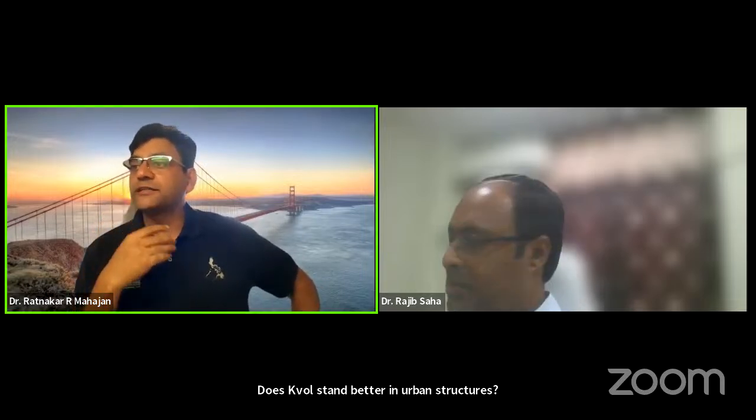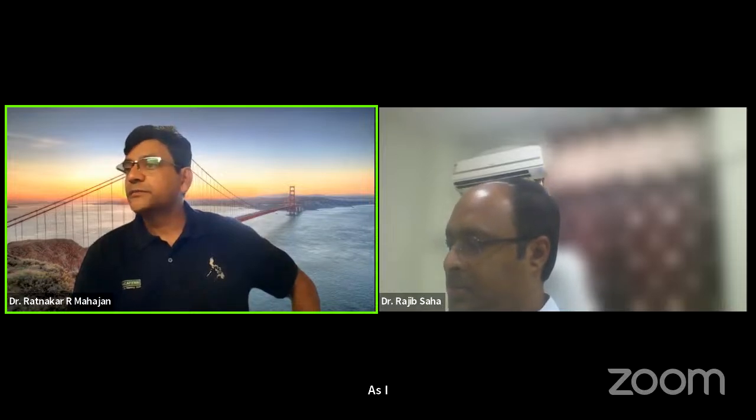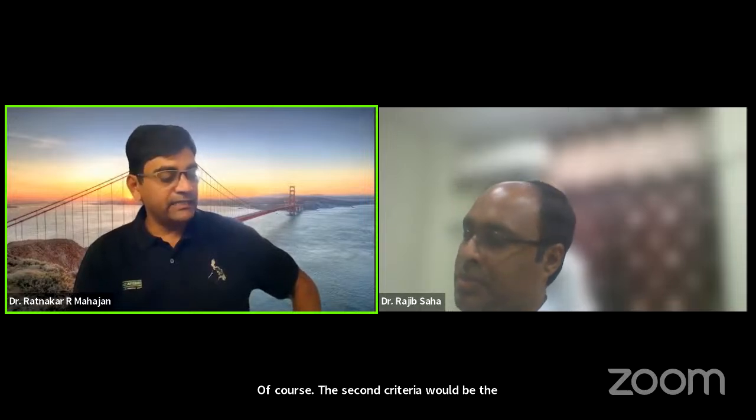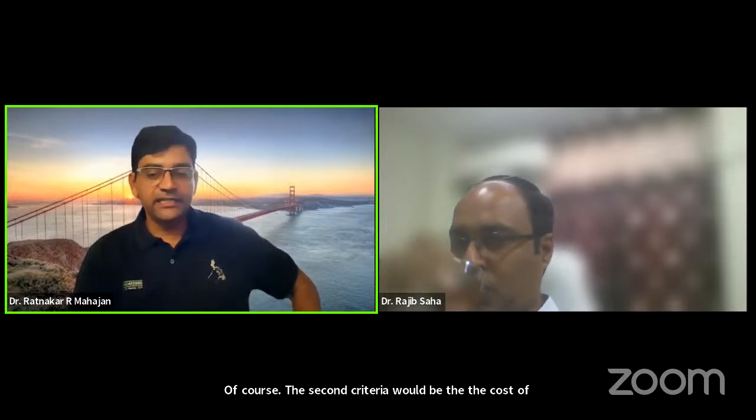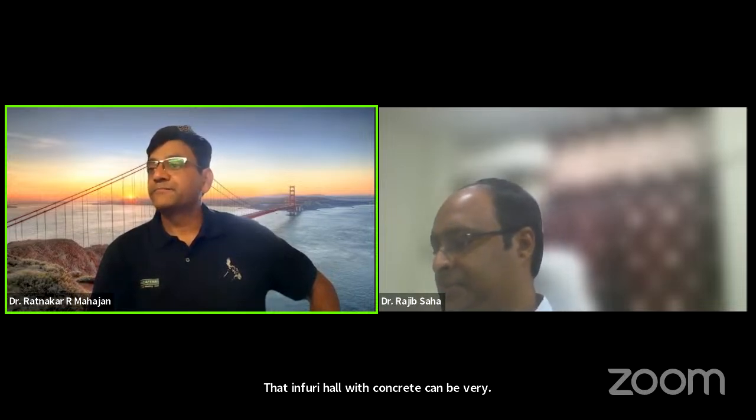Yeah, in terms of the cost for the same loading conditions, of course, as I explained, the mass gravity walls are economical up to 4 to 6 meters, and beyond that, the reinforced soil walls become economical. So height is one criterion. Of course, the second criterion would be the cost of stones. In case the cost of stone is very negligible, because it is coming from excavation, the gabion walls can even be cheaper for higher heights. But in case the stone cost is very high, in that situation, the reinforced soil wall with concrete fascia can be very economical. Thank you.